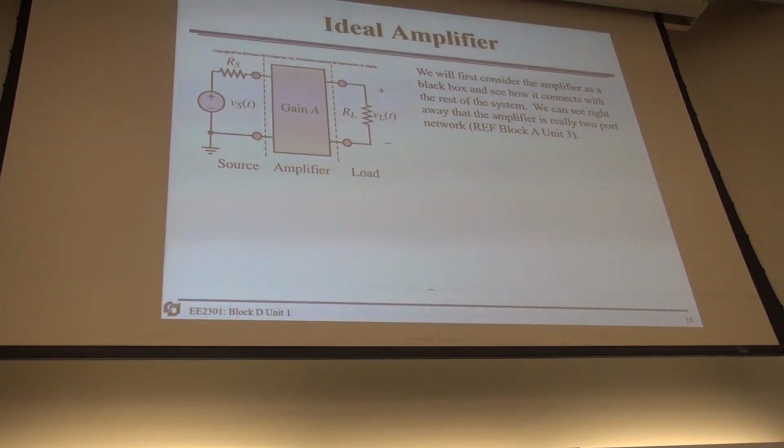So the dashed line here, inside here, this is an ideal amplifier, but the signal source is a real source. It must have some sort of R sub S. The R sub S is never 0. Okay? And then you have load, R sub L. L stands for load.